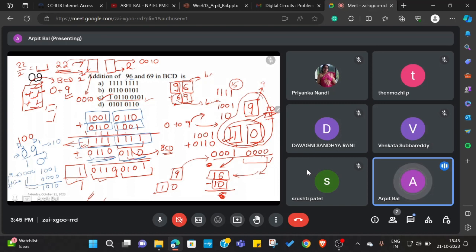So the correct amount between them is 16 minus 10, that is +6. 16 is the equivalent representation in BCD, and 1010 is the actual representation in binary, and the error between these two is actually 6. Because of this reason I need to add +6 to the binary values to get to the BCD number. Is that clear?